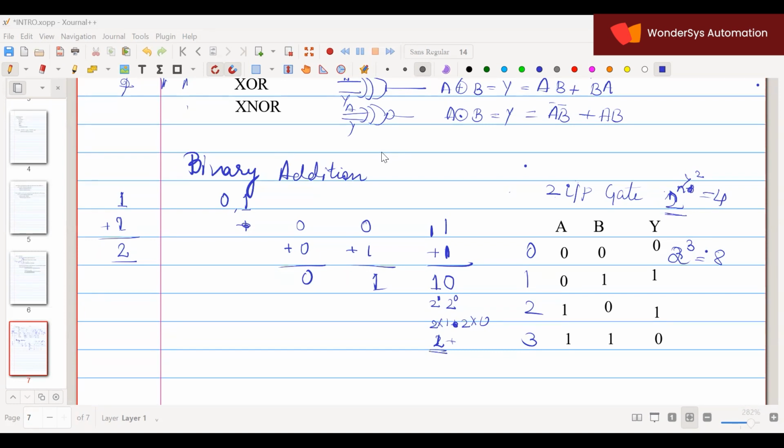Whenever we are using multiple switch and output combinations, we'll first write the truth table, then we'll implement it in the ladder diagram. That's why I gave so much time for basic gates. So this is very important. Whatever multiple switch and lamp combination or sensor combination they ask you, try to imagine it in terms of binary gates, it might be AND or OR operations. So it will be easier for you to write the ladder diagram.